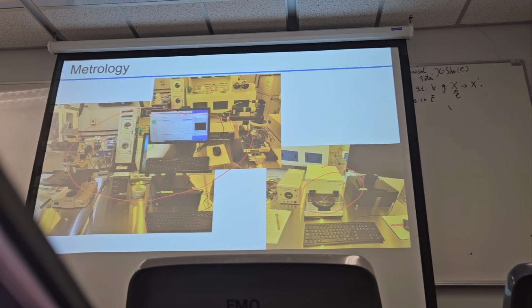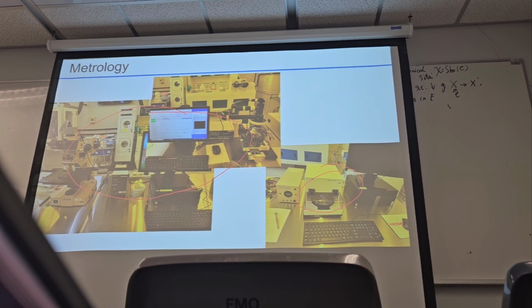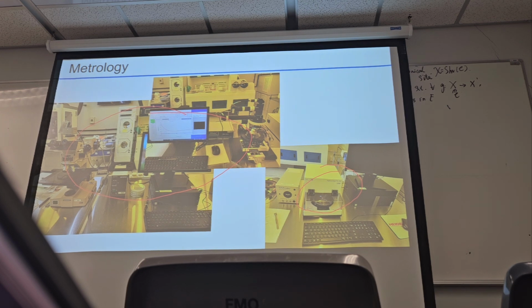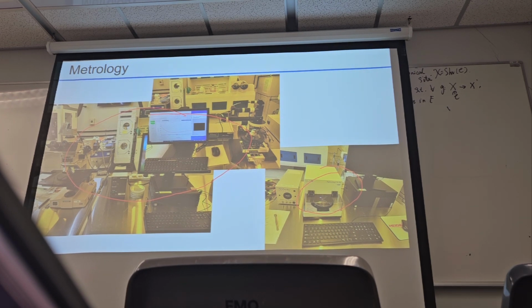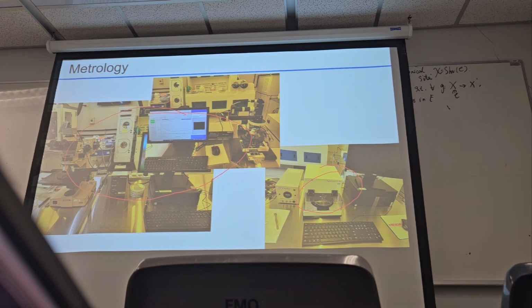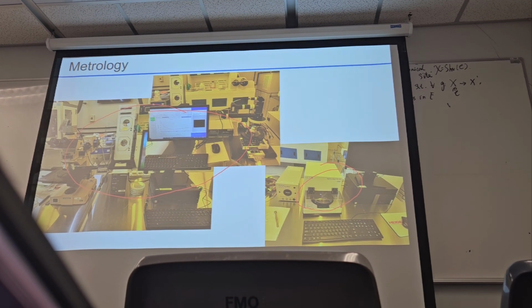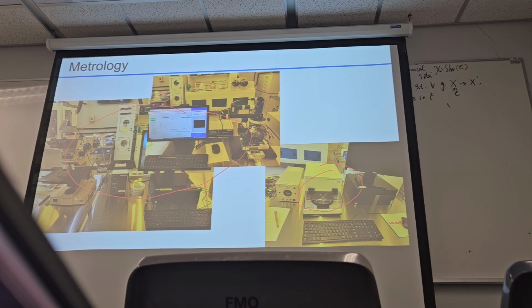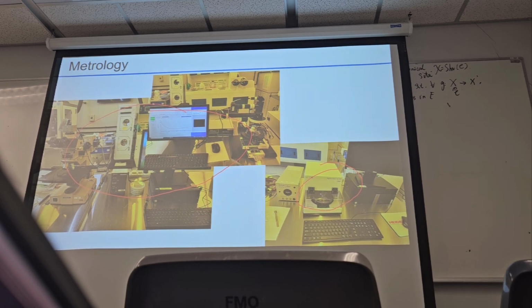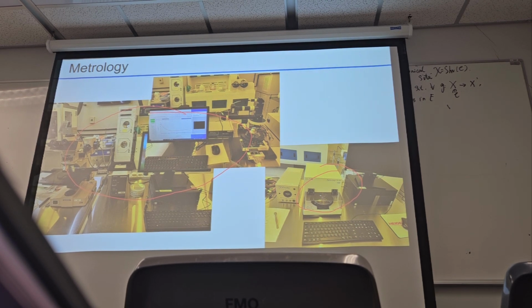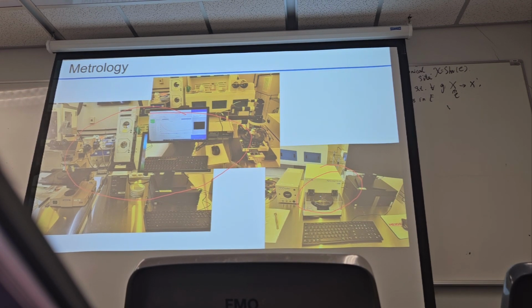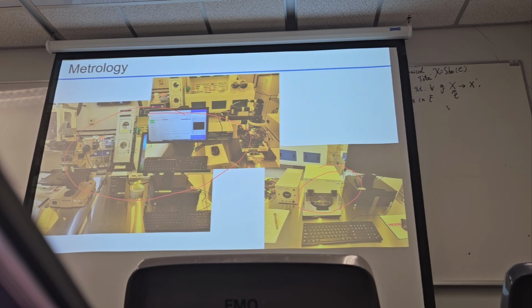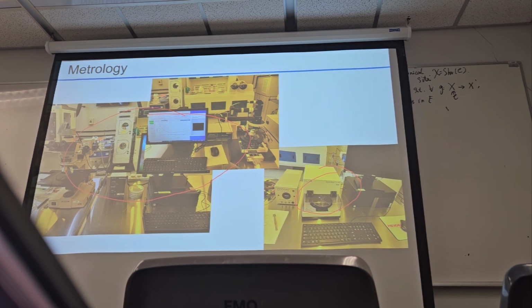For the first one, we need to understand the optical properties to do the fitting. Another one we can measure, right? We can measure the optical property and then measure the thickness. And for the profile step meter, we do not need to understand what kind of material it is. We just do the measurement. It can tell us the thickness, which is more accurate compared to the previous one. But the issue is you need to etch through the material. You need to do the etching.